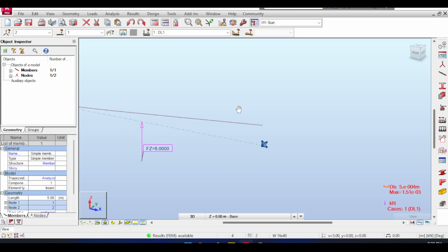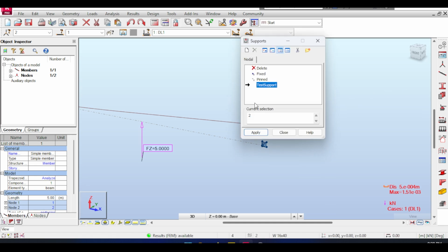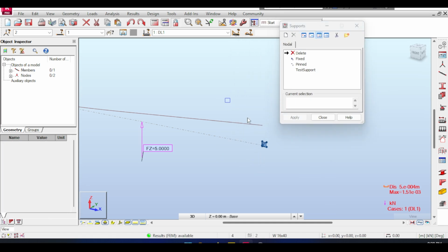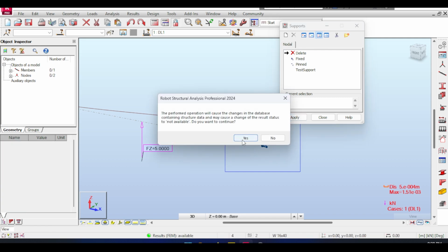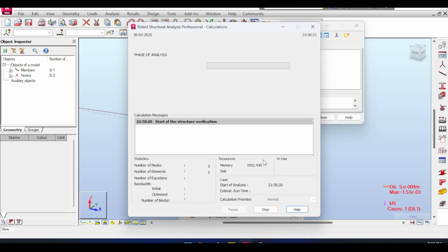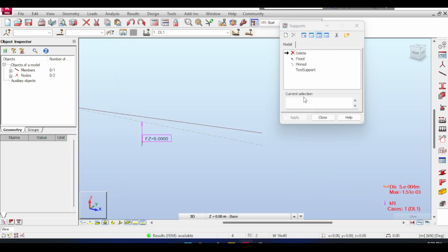Fantastic. So far, so good. Now, this deflection, 1.51, would also be obtained if I don't have any support, because that's basically a dead support. Meaning, if I even delete the support here and remove it entirely and run, keep an eye on that number. If I run that again, I get 1.51, no surprise at all. So this support is basically dead, it doesn't do anything.